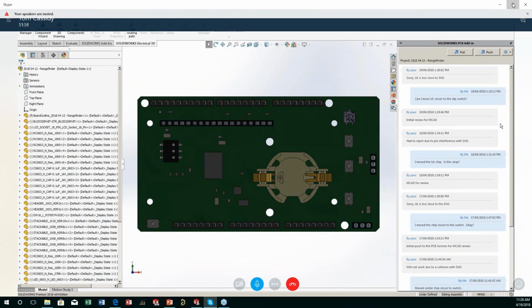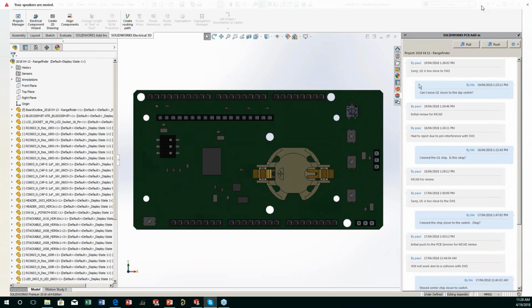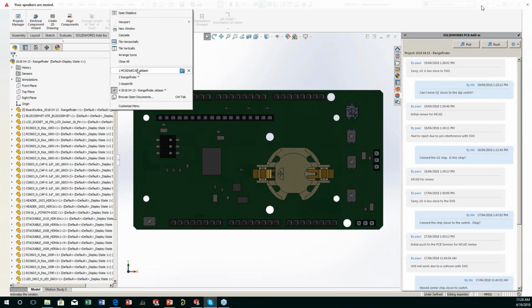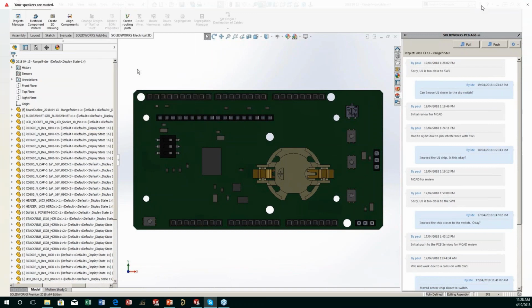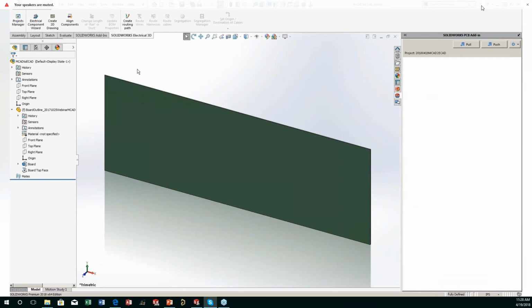So Tom, why don't you bring up the other example. So in some cases, what happens is that on the MCAD side, you initiated the design beforehand. So you've already started to draw it out. Maybe marketing came over and said, hey, we need this particular enclosure. We want to see how this is going to work for our marketing purposes. So you've already started the mechanical side of it, and now you've got to fit some type of printed circuit board in there. So this is now MCAD driving the shape of the printed circuit board. And so that's what you're seeing on the screen over here.